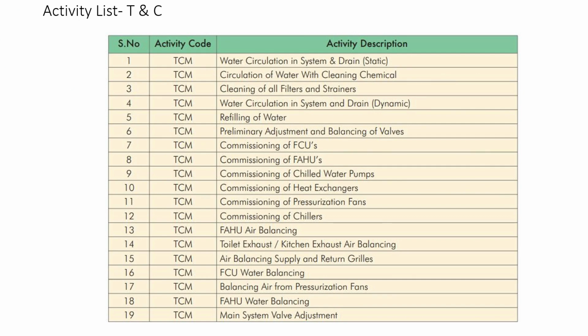But in the worst scenario you will face the chiller project because that's a complex and bigger one, so I am explaining from that point of view. In your case, if you have to install any DX equipment, you can replace the FAHUs with that DX equipment. The procedures and the type of fix and everything will be the same.